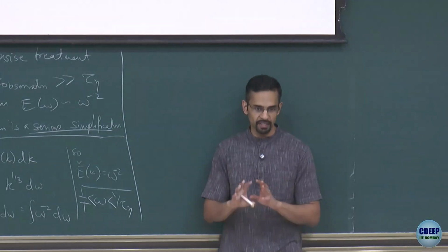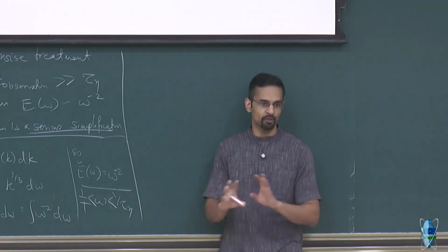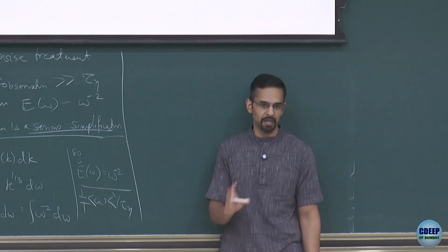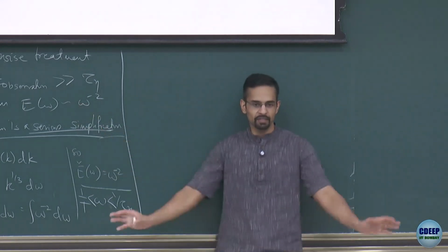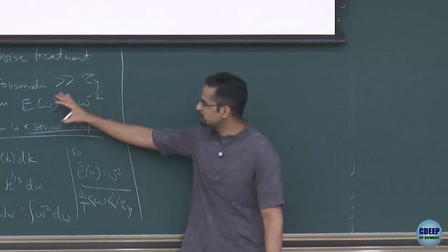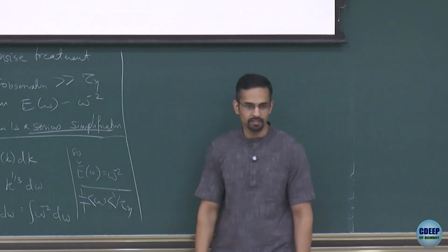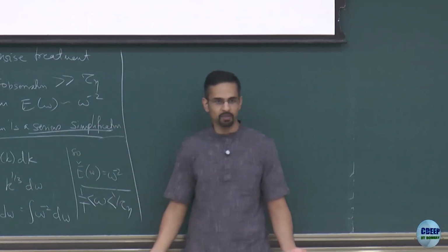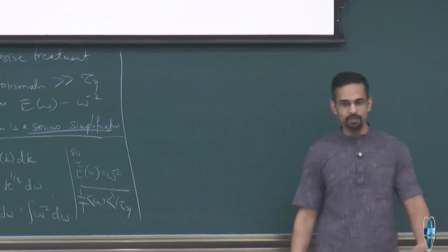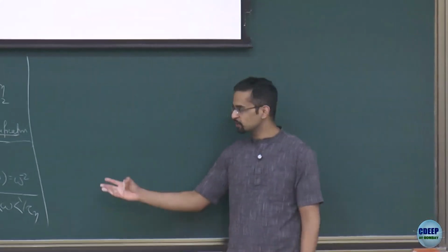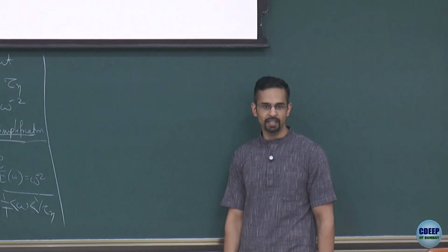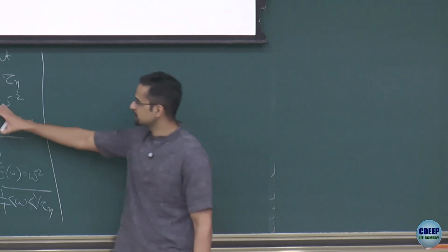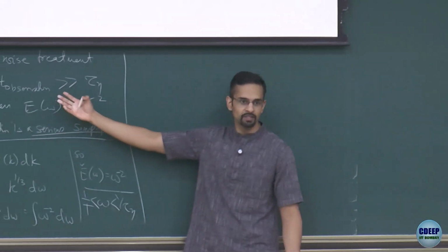But we should remember that we have basically replaced a flow that is correlated at all time scales by something where we are saying that beyond some time scale of my choosing, everything decorrelates. So I'm throwing away all these correlations at all the time scales smaller than this. That's a big approximation. And therefore, the deviations we see from real observations, from this sort of stochastic modeling that we'll be doing in the next few classes, will be affected by this. That's why turbulence is not a solved problem.